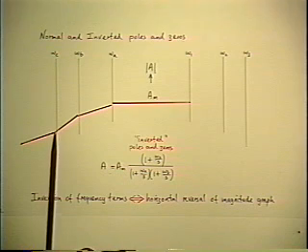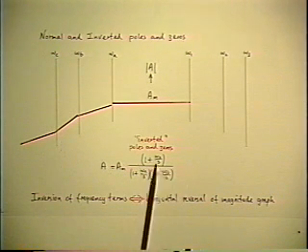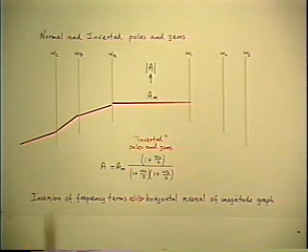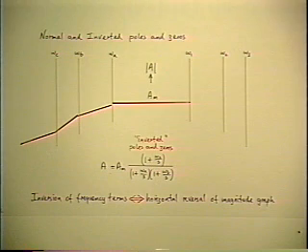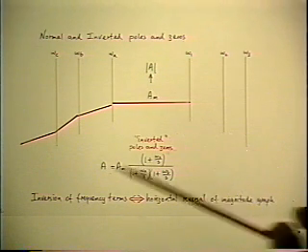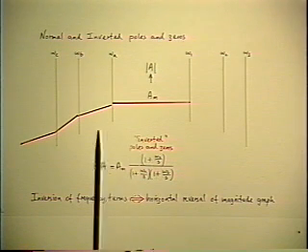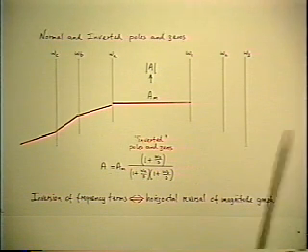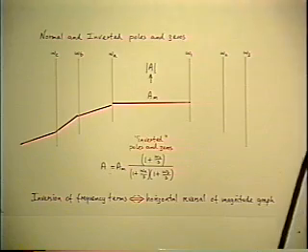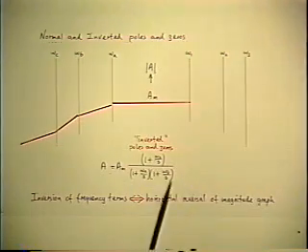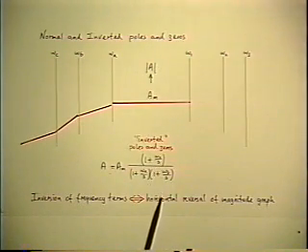And finally, concave upwards corner at omega C, so that's a zero, but it's an inverted zero because you're going down in frequency. So it's simply a matter of what is the reference direction of the change of frequency. If you're moving up in frequency, poles and zeros are in so-called normal form. If you're going down in frequency, they're in inverted form.